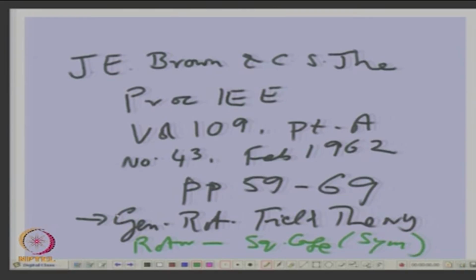Any type of stator configuration, any type of disposition of the stator winding, any number of stator windings, it will take care of, in the rotating field equations, where we can calculate the currents for the given set of voltages and also the torque. We calculate the torque as the total air gap power divided by synchronous speed for different fields. Whatever power you feed to different fields will give the respective torques.